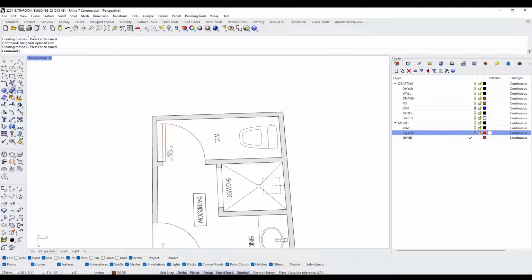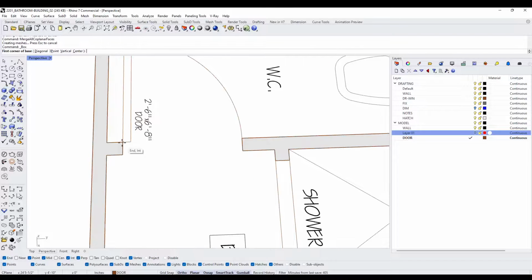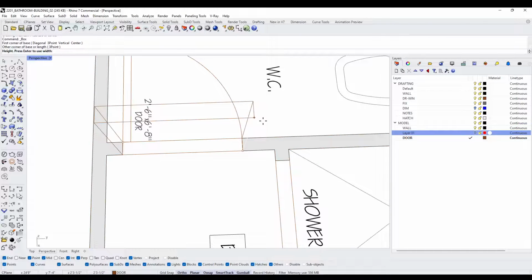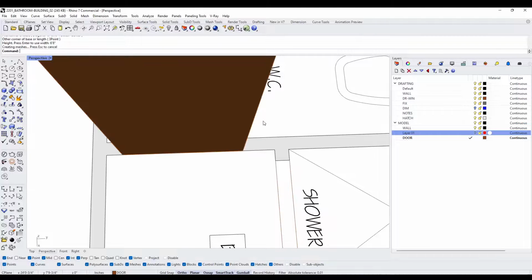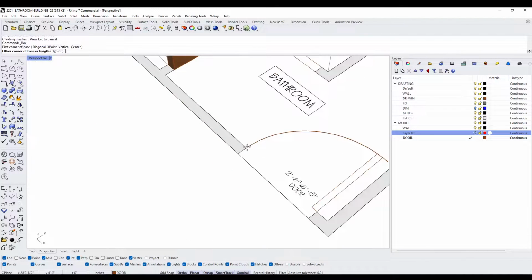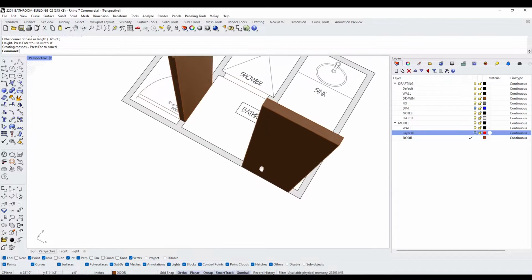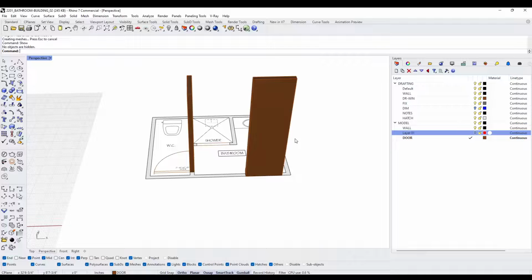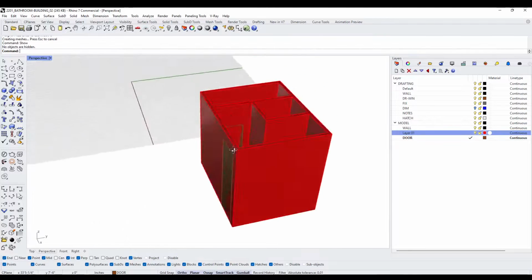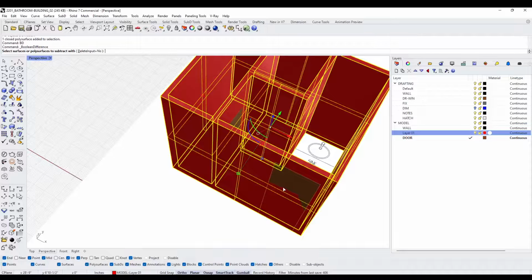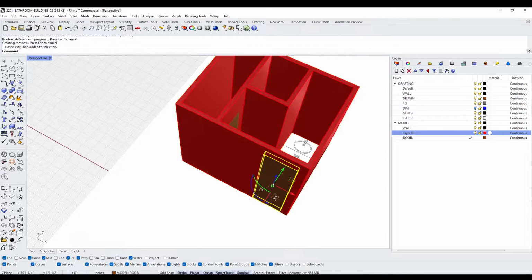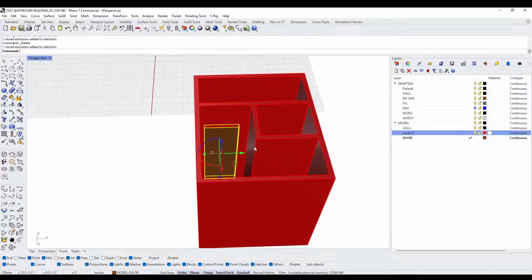that wall. Now let's bring in an extrusion. So we'll go to a box from here to here. We'll go 2 feet 6 or 6 feet 8 inches. We'll do here 8 feet. Now here we'll type in show, or we'll bring back the wall, and we can do Boolean difference to subtract the doors. So rather than building up the walls, we're actually just subtracting the door.